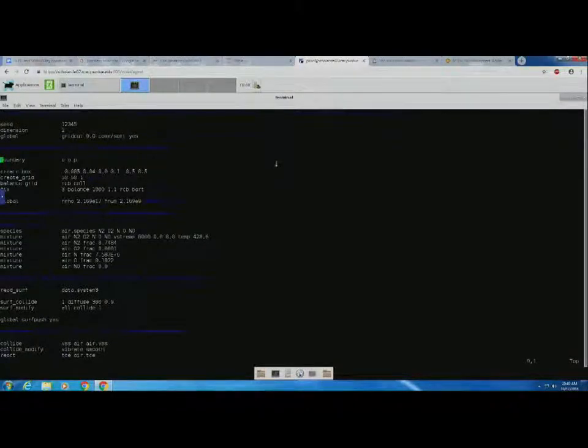So here, boundary specifies what you want the boundary of the domain to be. Create box is where you say how big you want your simulation domain to be. In this case, I want my box to extend in the x direction from this dimension to that dimension, and in y from here to here. For the z, if it's a 2D problem, you just make it negative 0.5 to 0.5. For a 3D problem, you change it to something you actually want.